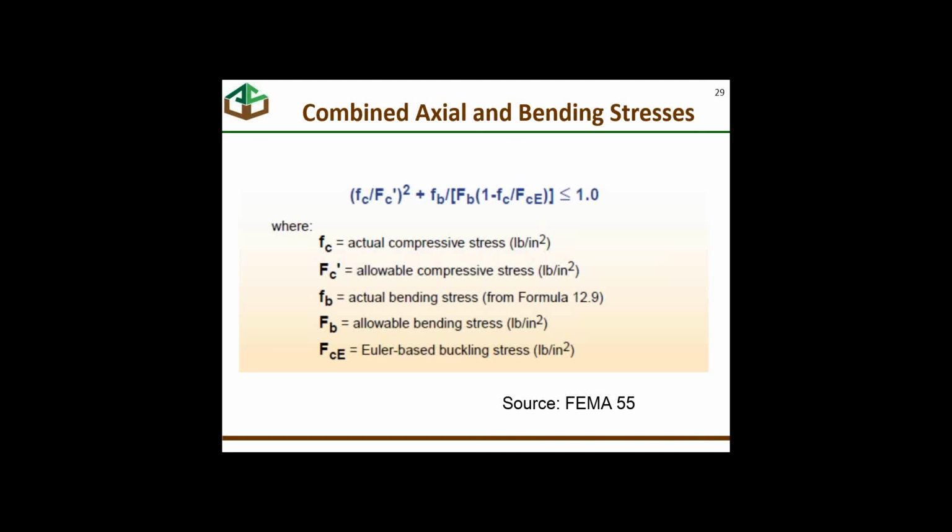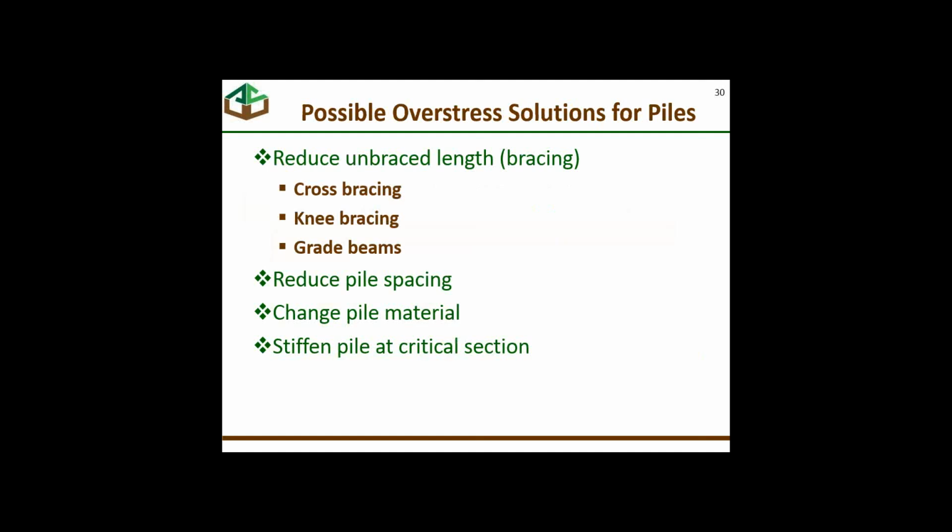I would do that by figuring that the bending stress, F sub B, is driven off of a cantilever beam. So the moment is L times whatever the force is. So anyway, that's a frequent way to handle this without getting too wrapped around the axle about what the length needs to be. We certainly have some overstress solutions for piles if in fact we go through all this